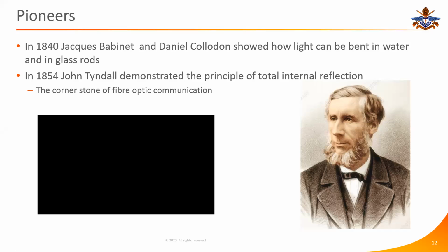That was a quick introduction to how fiber optic cables are made. So fiber optic cables have a core which has a slightly higher refractive index and a cladding outside that, which has a slightly lower refractive index. A fiber optic cable is the size of a hair. The internal core is about 10 microns. The outside cladding can be up to about 100 micrometers. So you can imagine a single optical cable is only 100 micrometers in diameter, smaller than your hair.